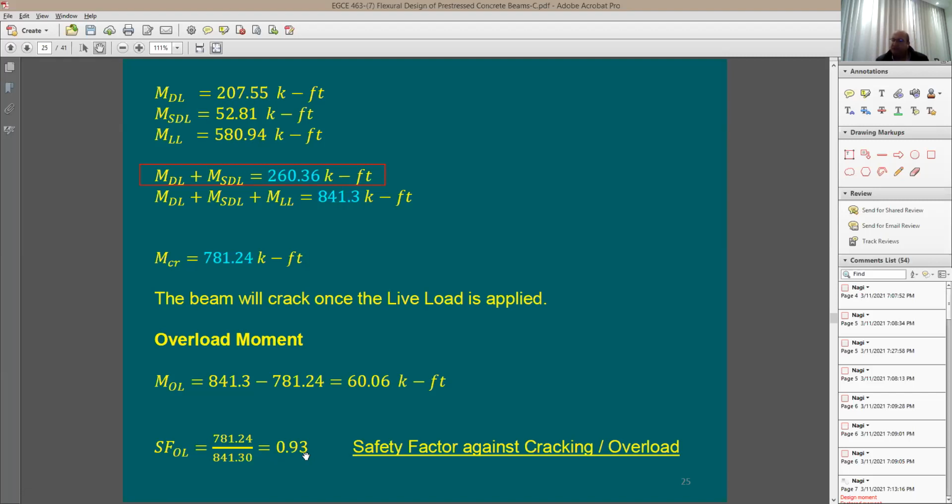If you have a beam that's designed not to crack, I'm expecting the safety factor to be at least 1.0. So if you see here a value of 1.5, what does it mean for you? It means at 2/3 of the load, or 2/3 of the cracking moment, the load was right there. In other words, the applied load here will cause a moment which is nearly 2/3 of the cracking point. So you still have way to go.